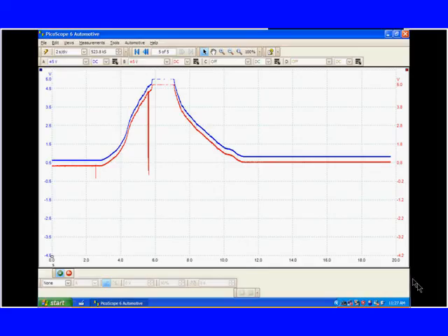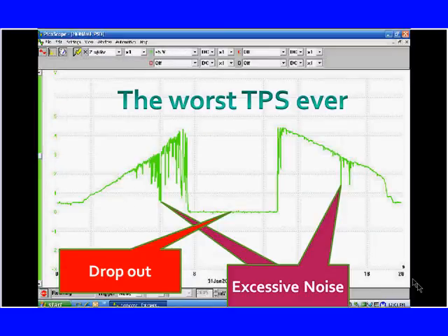So this is an important way to find problems that do not set a code. Let me say it one more time. This is the way we find problems that do not set codes. Why? Because it may take whatever. One code said it took 1 second. 1/2 of a second is 1/2 division on 2 milliseconds per division. This is definitely not fast enough for that.